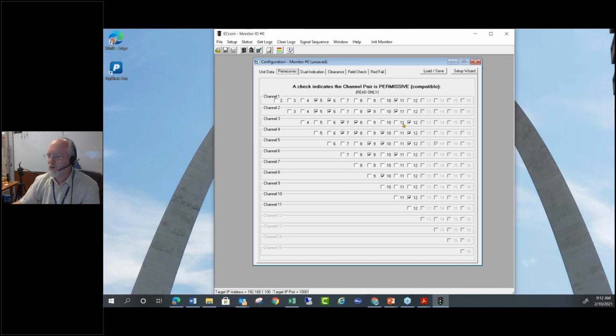So if you're out in the field and you want to know, is my program card correct, you can bring up this software. What's nice about this is you can say, okay, in this case, channel 1, 5, and 6 is on. Let's say you go out there and they say there's a conflict, and you go, well, wait, I looked at my program card, I can see 5 and 6.